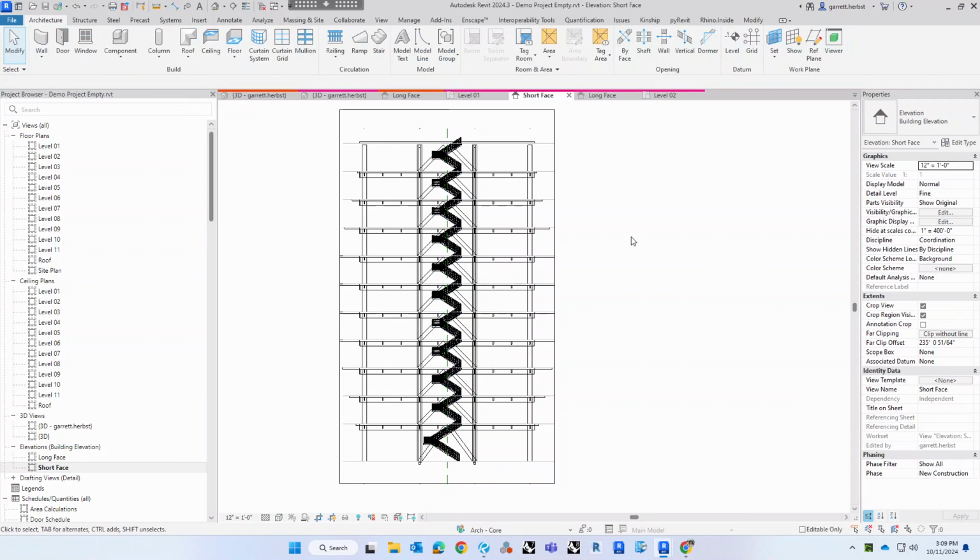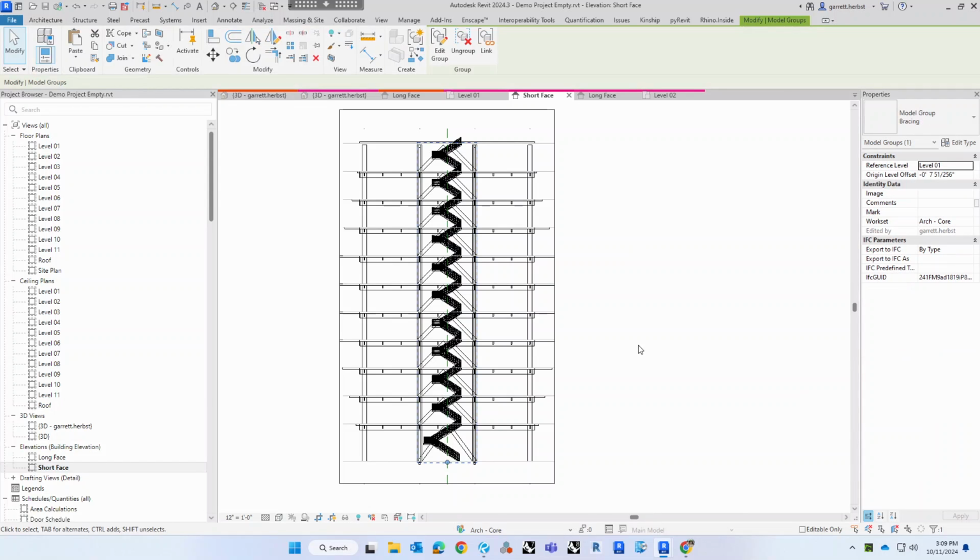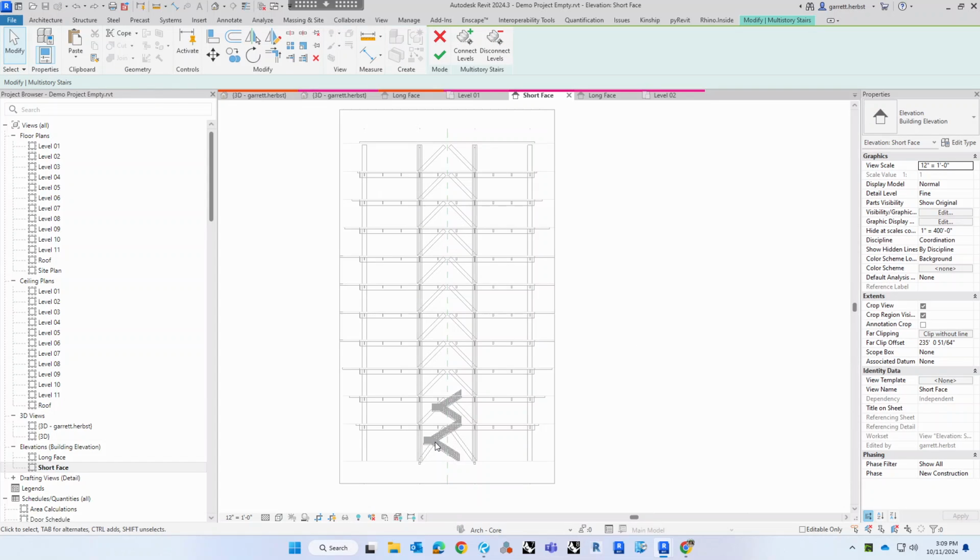So it figures out the first floor. So like if I did the first floor and then I'll do that right now. It's just you don't have the same level of specificity with it that you do if you know that it's the same height. So if I did select levels, and then did all those, yeah, so it works. It aligns all the landings back up.